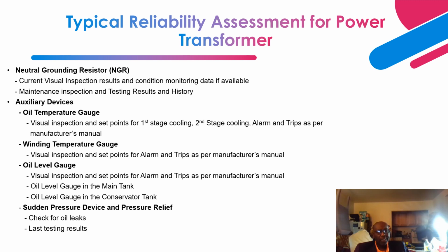What you want to do is basically perform a visual inspection of the neutral grounding resistor. A lot of times, what I've seen is there's a lot of accumulation of dust on the grounding resistor. So you want to check the condition of the dust.